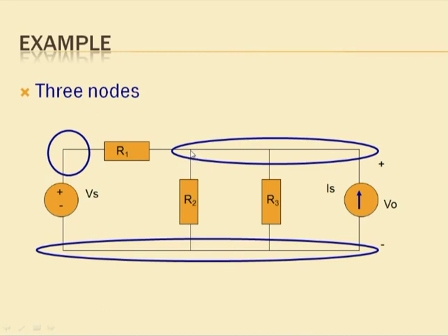That means if I am measuring the voltage at this point with reference to ground or say the negative of the battery, then whatever the value I found, the same value I will have if I measure the voltage at this point and the common reference that we identified.